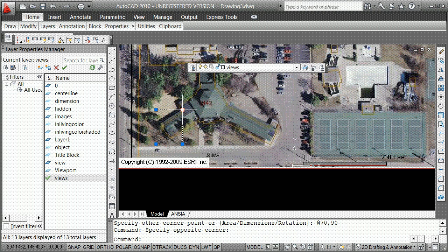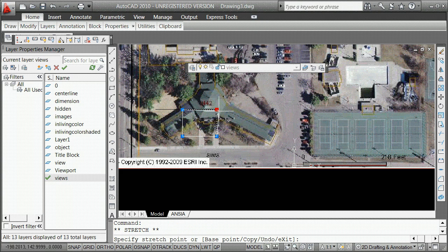So watch how you're doing this. I've selected, left clicked, clicked spacebar, rotate 90 degrees, and I've just used a snap edit. Another huge thing to start using in Civil 3D. I am going to move that. Let me try it again. I'm selecting, left clicking, spacebar, move. I can move that where I want to be. I can left click, spacebar, rotate.